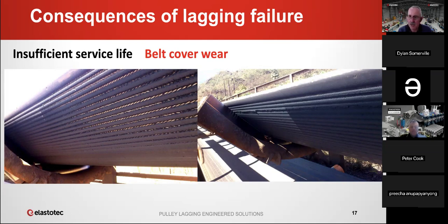This particular photo was on a turnover conveyor, and there were very high shear forces on one side of the conveyor, and the non-drive pulleys were wearing out in a band on one side and had to have the lagging replaced every roughly 3 months. So one of the maintenance people decided to put a piece of ceramic lagging where the wear was occurring, and they did fix the lagging. The lagging lasted a lot longer, but the wear was transferred onto the belt bottom cover.